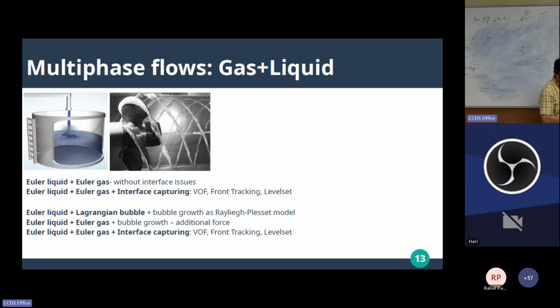So with the same multi-phase flow systems, if you have that kind of application, you will use Euler, as we will see. If you have the same application with a little more complexity, you will have Euler with interfaces. The same problem, but millions of bubbles are also coming, because that phase is also present, the liquid phase is also present. You will go with Euler, maybe with additional points. If you have chemistry, like sonochemistry that happens when these bubbles burst, again you need to activate those chemistry modules. It's not straightforward, it's jumping around the solvers.